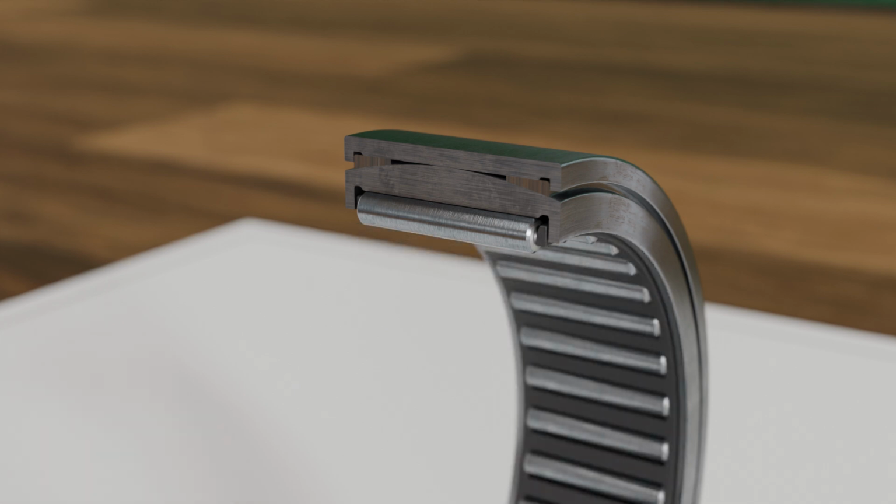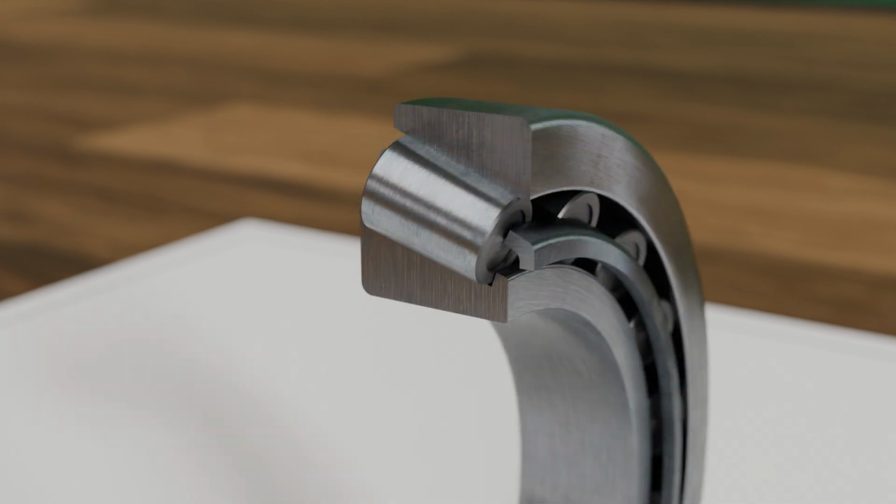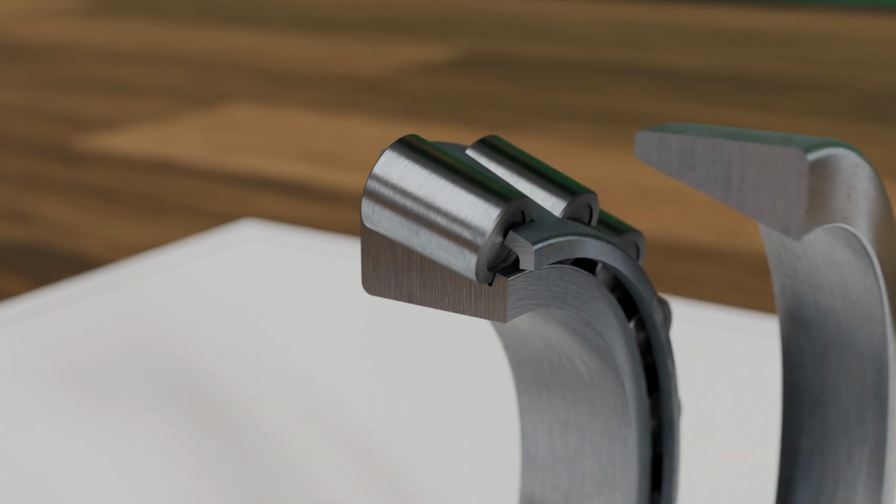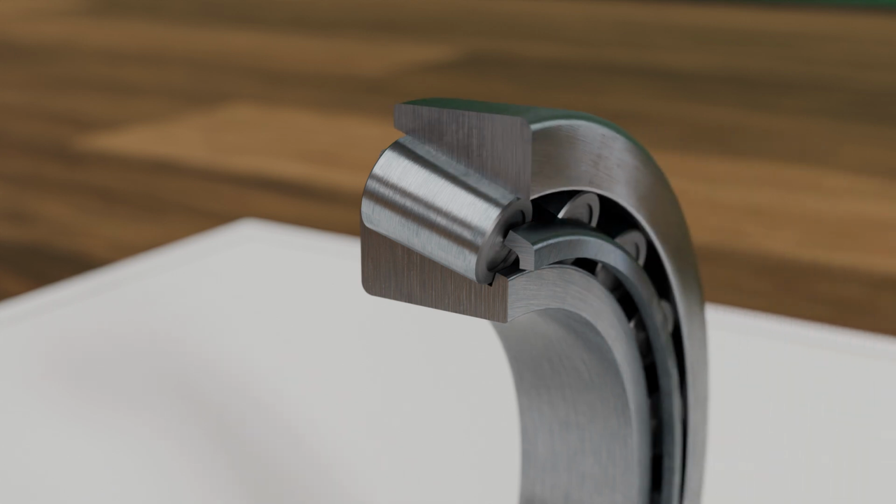As already explained, cylindrical roller bearings or needle bearings can only take up axial forces to a limited extent or not at all, depending on their design. To simultaneously absorb large axial forces, tapered rollers are used instead of cylindrical rollers. These are called tapered roller bearings. They are usually non-self-retaining bearings, as the outer ring can be removed and mounted separately from the inner ring.